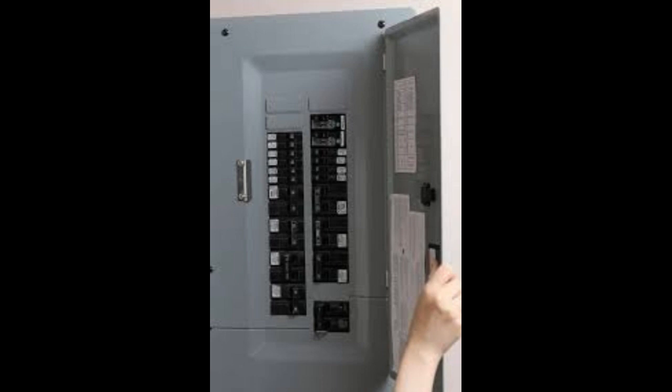4. Missing or damaged receptacle, switch or junction box covers. 5. The absence of: 1. Equipment disconnects, and 2. Appropriate connections, such as copper/aluminum approved devices, if branch circuit aluminum conductors are discovered in the main or sub-panel based on a random sampling of accessible receptacles and switches. 6. Receptacles less than 5.5 feet above the floor that are not tamper-resistant.